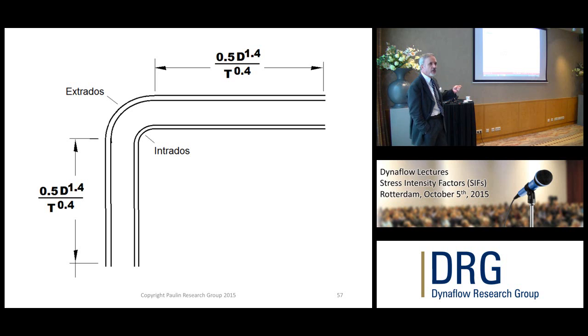The worst bends that we see are short radius bends. If you've got D over T greater than 40 and a short radius bend, the code equation right now is just not very good. It just wasn't intended for that. The code equation was developed back in 1904, and it assumes that you've got uniform ovalization all along the bend arc. So you've got uniform ovalization up to the straight pipe, and all the straight pipe is ovalized through about this length. Well, that's just not what happens all the time, right?